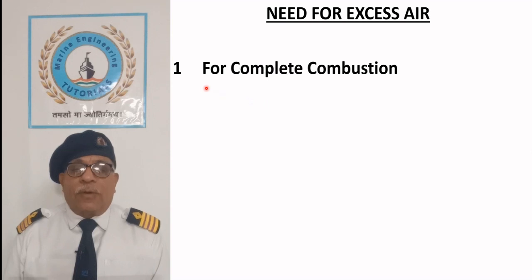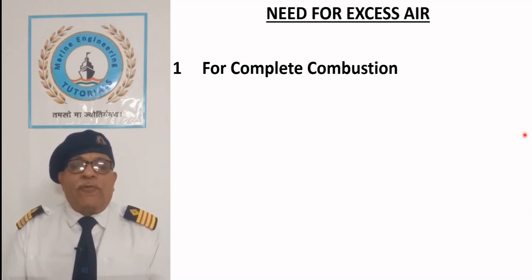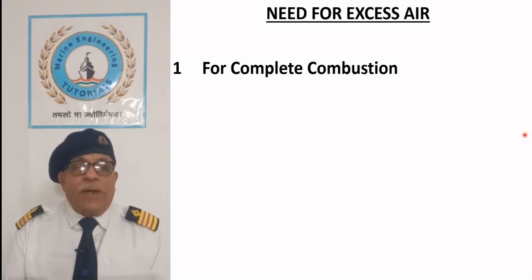For complete combustion, excess air ensures that there is enough oxygen available for the combustion of all fuel particles. This helps in achieving complete combustion, where fuel is burned completely to produce carbon dioxide and water vapor, minimizing the formation of harmful pollutants like carbon monoxide.